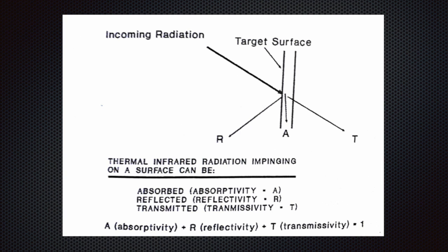The two main sources of error for an infrared thermograph include the loss of energy as infrared radiation passes through the atmosphere and the infrared radiation that is reflected off of the screen or detector of the thermograph. Regardless of the radiation absorption method, some of the radiation will be reflected, resulting in less radiation absorbed, a weaker electrical signal response, and a lower reading. One way to mitigate this error is to install a reflective pane on the inside of the device that allows the radiation to travel into the sensor, then reflects any outgoing radiation back to compensate.